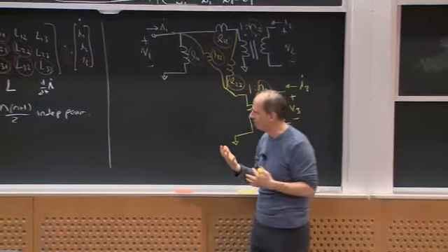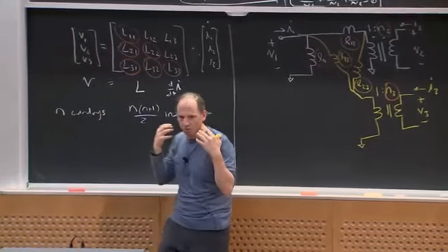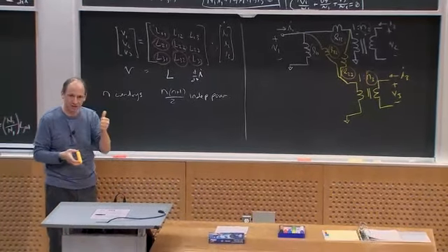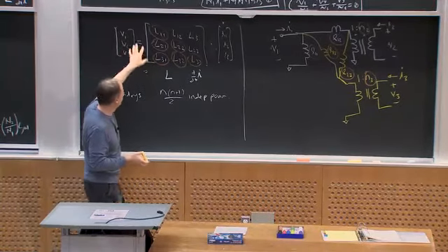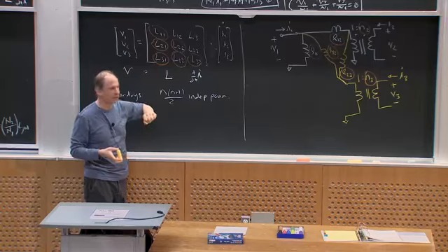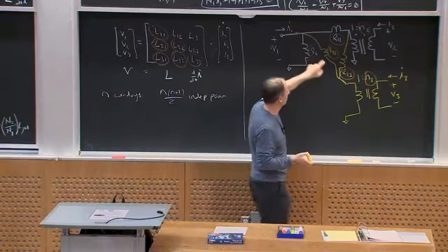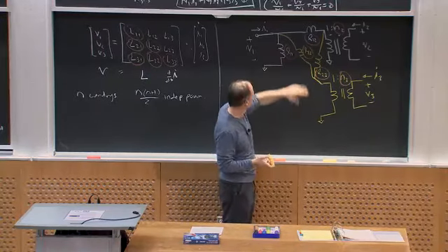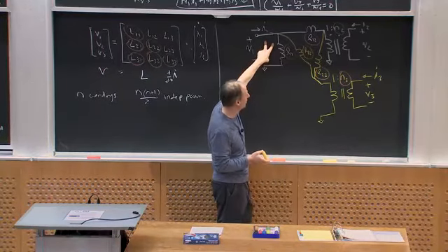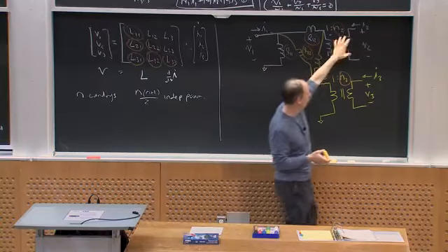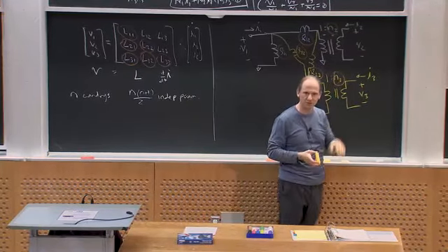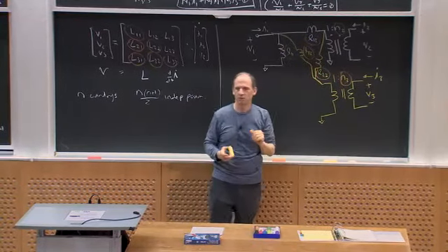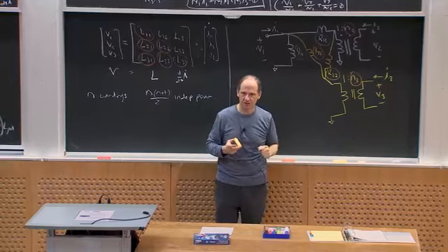So I'm sort of running out of time, but what I'll tell you about this model, and the details are all in the text, is that the nice thing is, firstly, there's always a set of measurements you can do on your circuit that will reveal directly what these ratios are. For example, I can find L11 just by open circuiting everything and measuring the inductance at this port. If I put a voltage here and I measure all the voltages at the other terminals, that gives N2, N3, and so forth. There's a set of measurements I can do that will always reveal these parameters.